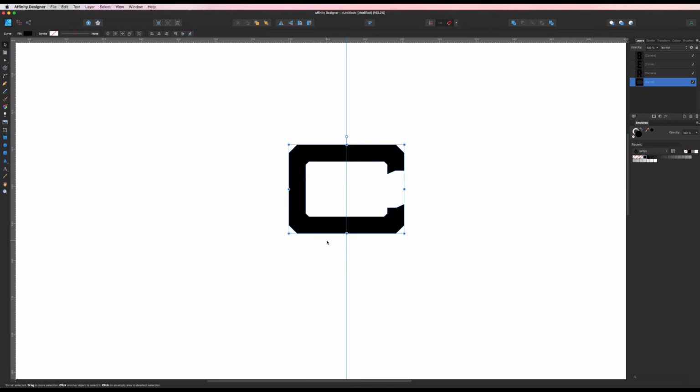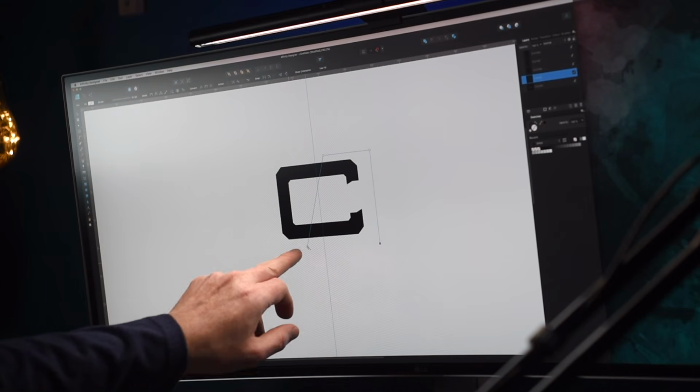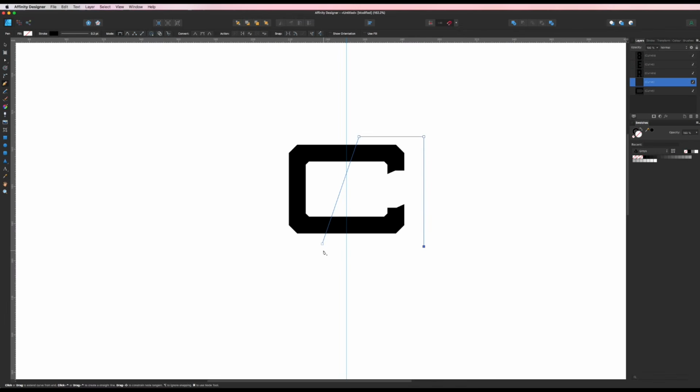So let's get our pen tool up. P, okay, this is this tool over here, the pen tool, and I'm going to click over here, and let's just close our object off by clicking, and closing it. Now you can see there's a little plus, plus, plus. So we want to close that shape off. So now we've got this closed shape over here. So this little curve over here, I'm just going to move to the top. That is our closed shape.